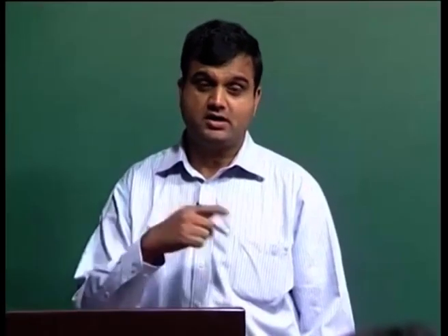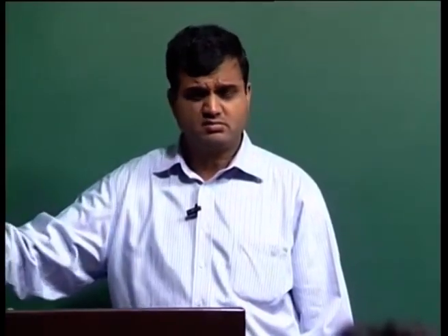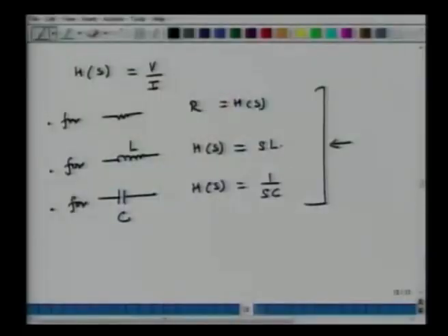And what about s, sir? s is again complex. It can be, as we saw in an earlier case, if you have vibrations and they are dampening over a period of time, it can have a real component and an imaginary component. And if it is a pure non-dampening vibration, then it will be purely imaginary. So we will do an example and see how we use some of these transfer functions to simplify circuit analysis.